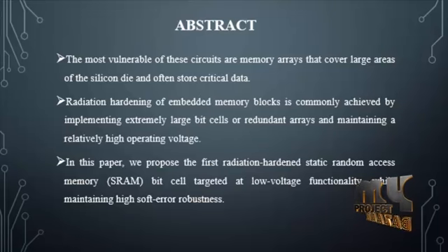The proposed 13T employs a novel dual driven separate feedback mechanism to tolerate upsets with charge deposits as high as 500 fC at a scaled 500 mV supply voltage. This is achieved with a cell layout that is only 2x larger than the reference 6T cell drawn with the standard design rules.